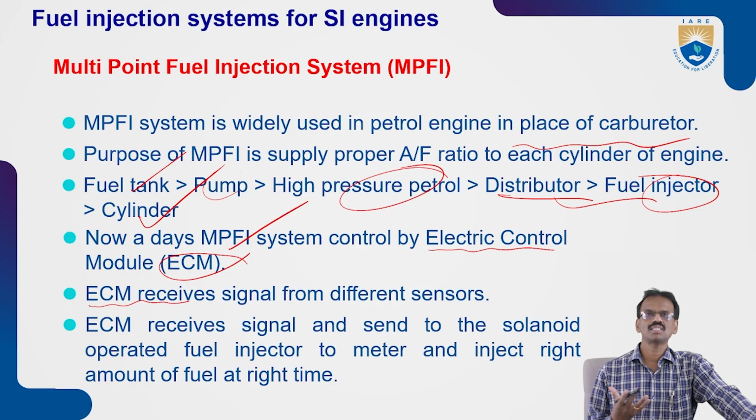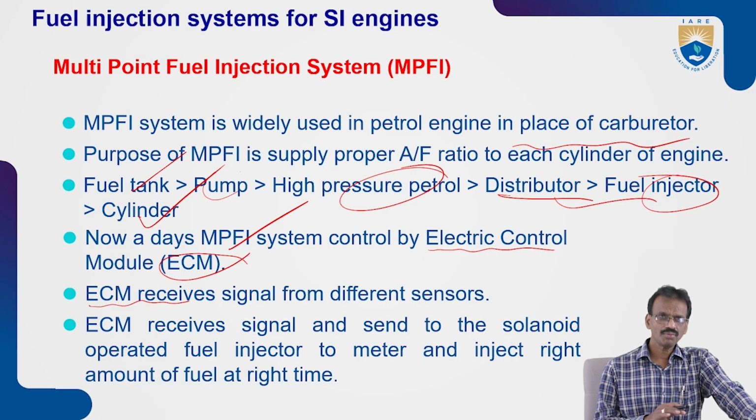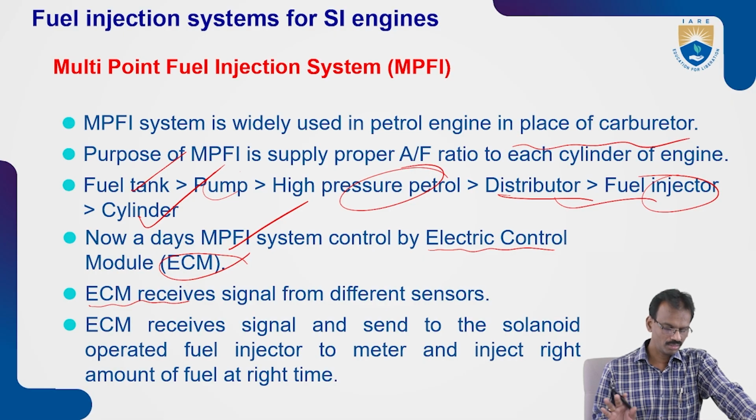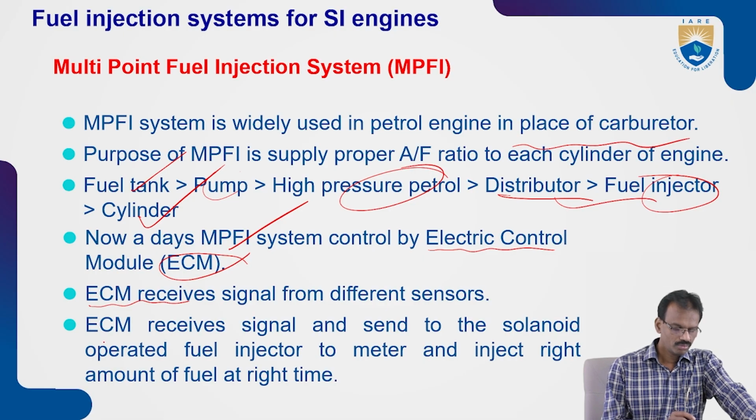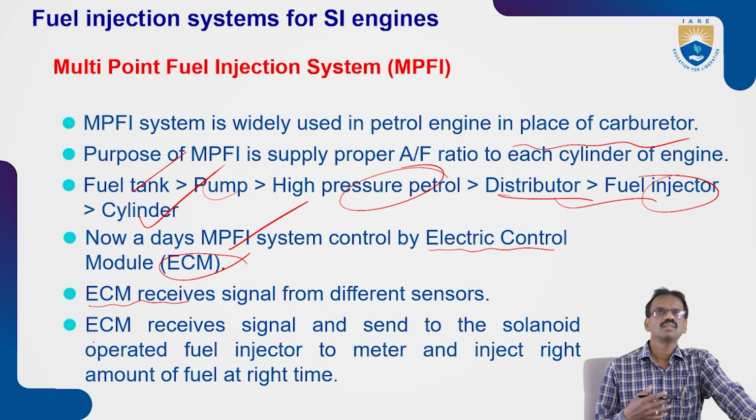So these sensors give the different signals. Based upon those signals, the ECM controls the multi-point fuel injection system. That supplies the optimized amount of fuel as per the requirement, without wastage of air fuel mixture. It also provides proper mixing.